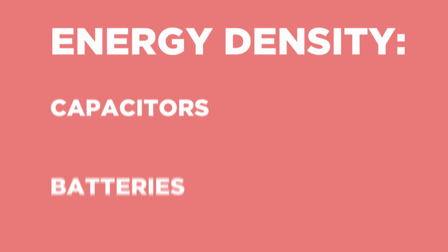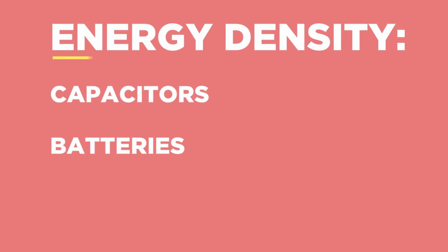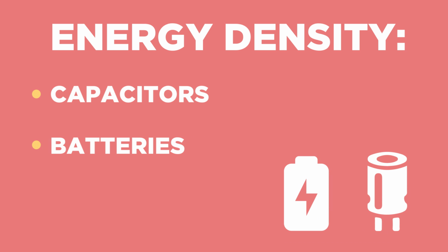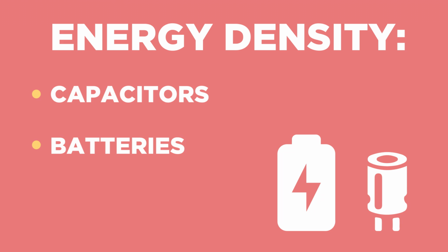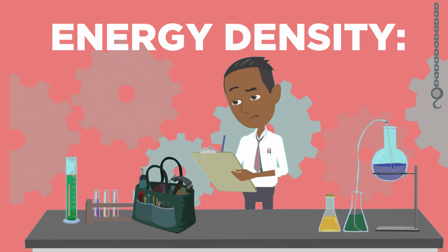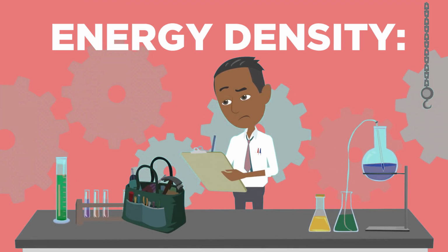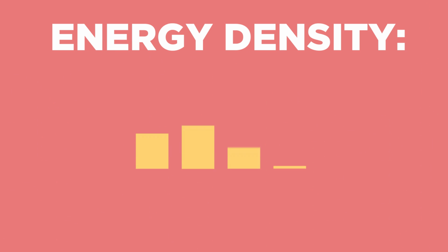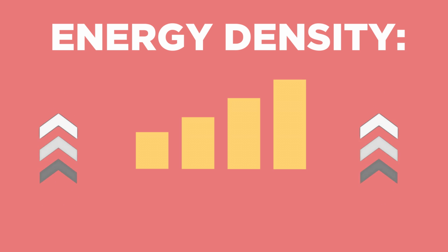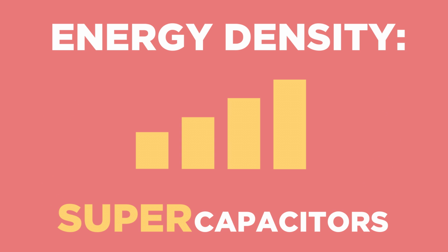The main disadvantage of such devices is the low energy density, especially compared to batteries. They can charge and discharge way faster, but the amount of energy that they can store with respect to their volume is really low. However, developments and discoveries in the land of capacitance brought new ways of generating and storing energy in an electric field, which increased the energy density of these devices. The reached values were incredibly high compared to traditional capacitors, and for this reason they needed a fancy name: supercapacitors.